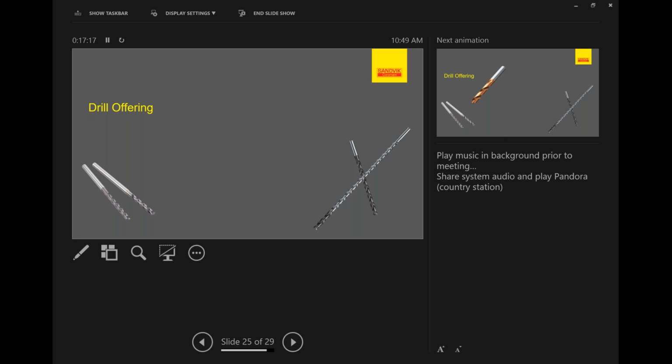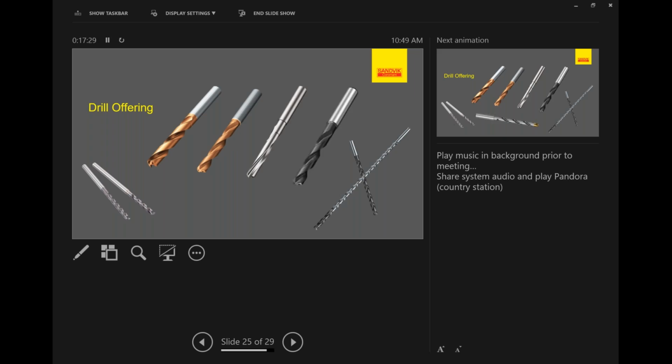You've got to have really good filtration so you don't get any kind of junk or dirt to plug a hole in those type drills. We have drills that are specific for steel, for stainless, for aluminum, for ISO-S, for nickels and titanium. So we really have the full gamut of tools based on your application.